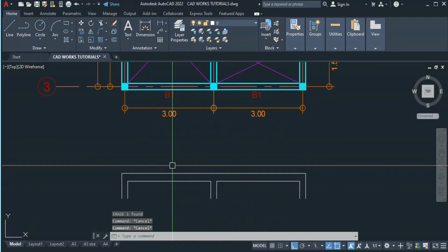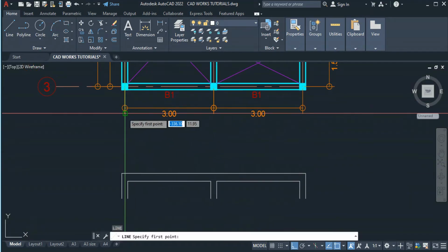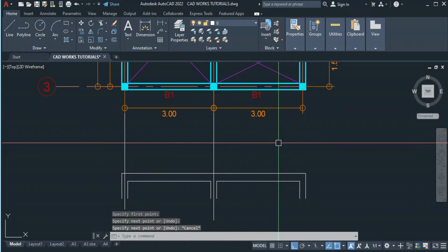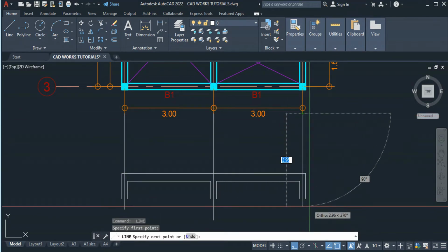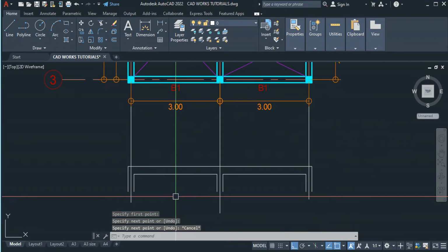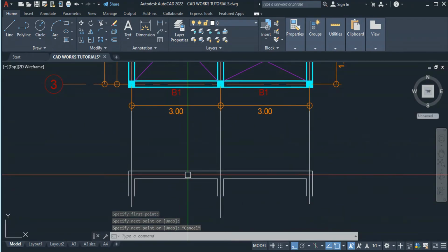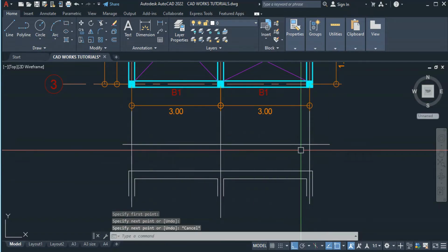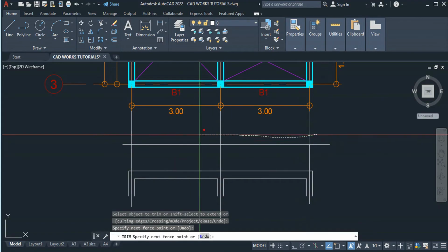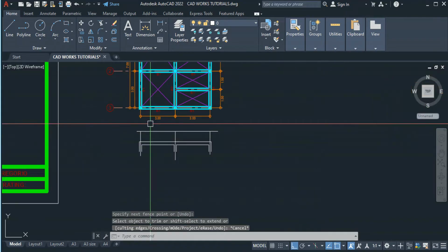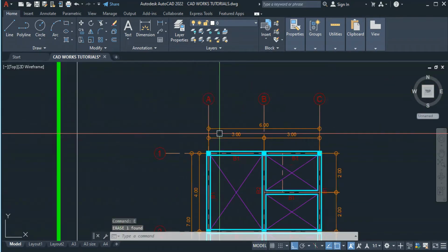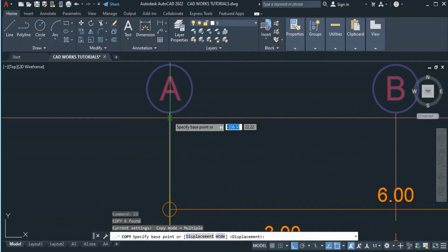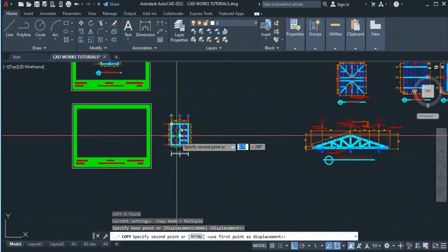Once I'm here, I'm going to create lines right away for my grid lines, so that along the way it will be easier. After that, I'm going to place a line in the middle here as my guide, trim the unnecessary marks, remove this line, then copy the letter grids and place them in their respective positions.